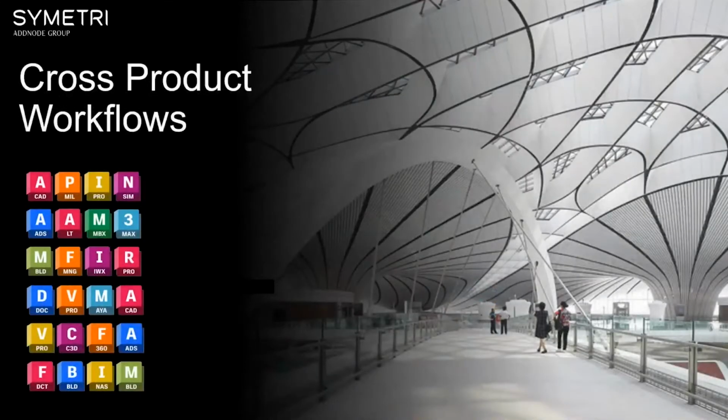Dynamo can also enable workflows with other design tools to help reuse information generated within Revit. For example, complex facades can be broken down into individual panels, refined and transferred to fabrication and manufacturing software such as Inventor. Mundane tasks such as naming families and renumbering elements can be taken care of in Dynamo, freeing you to concentrate on the actual design. Dynamo can also play a key part in generative design, where design problems can be refined and solved, giving the optimal solutions without having to spend many weeks on other design alternatives.